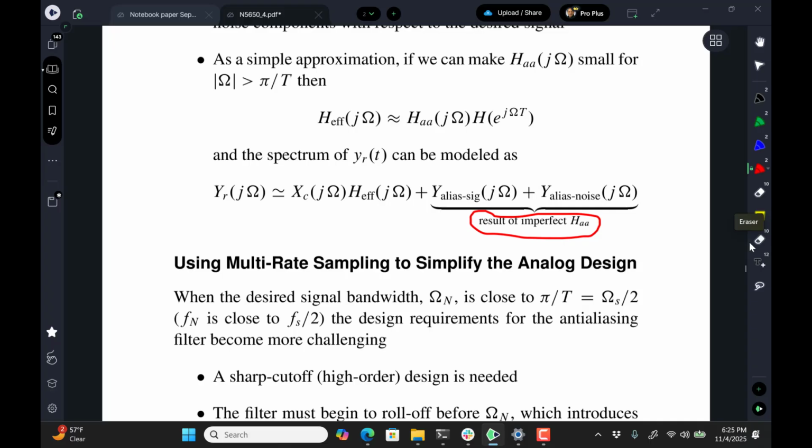If I'm speaking with my voice, a low-pitched male voice, and I'm sampling at 22.5 kilohertz, or no, 44.1 kilohertz, so anything above 22.05 in my voice is what's going to fold around and come back in again. Now, if you take an infant or a female voice, which would be higher pitched than mine, then there's more of a chance.